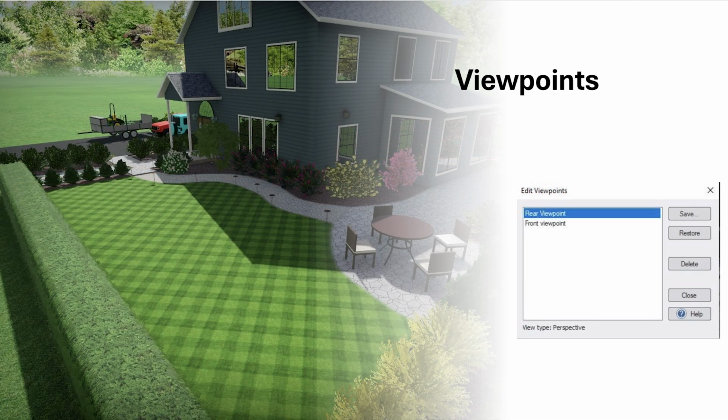The last tool we used in Real-Time Landscape Architect is viewpoints. Viewpoints are known as set views from the walkthrough tab that allows us to save certain views that we can return to at any point. While in the viewpoint, you are able to change the environment settings, and then you can screenshot different times of day. From there, you can save them and import them into the plan view to show different areas of the design. This feature is not used in AutoCAD and Dynascape.